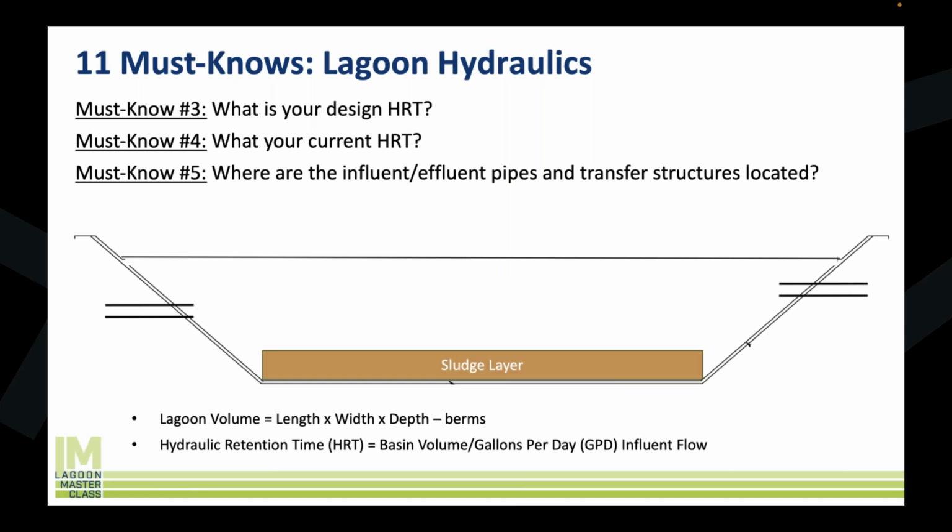I think I have two, actually. I think I have one on the effects of biosolids and one on how to measure them. Really important to understand where your biosolids are so you understand what your current hydraulic retention time is. The next point here that I'll just touch on is where are your influent and effluent structures.